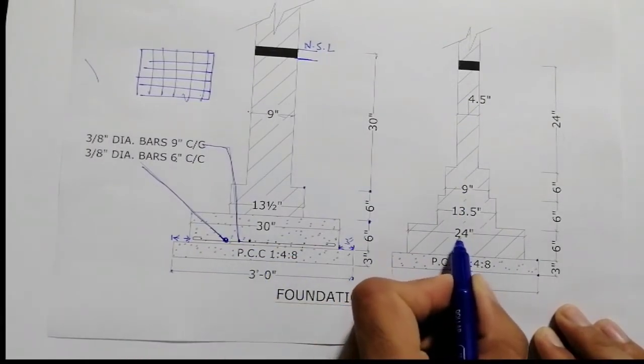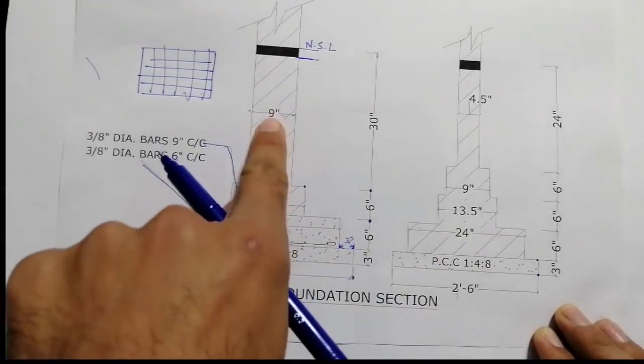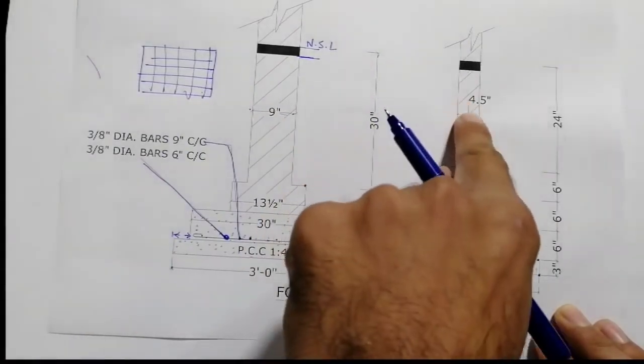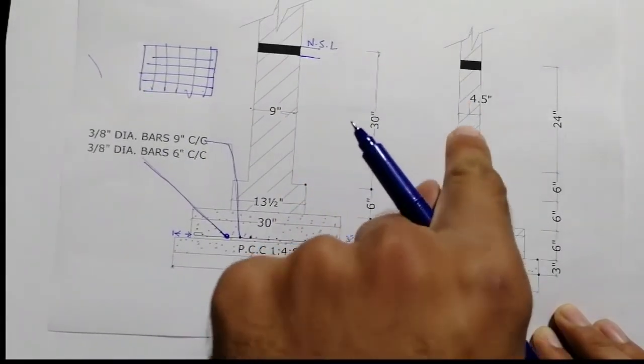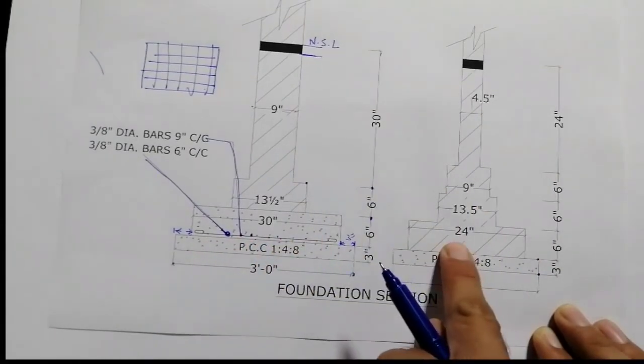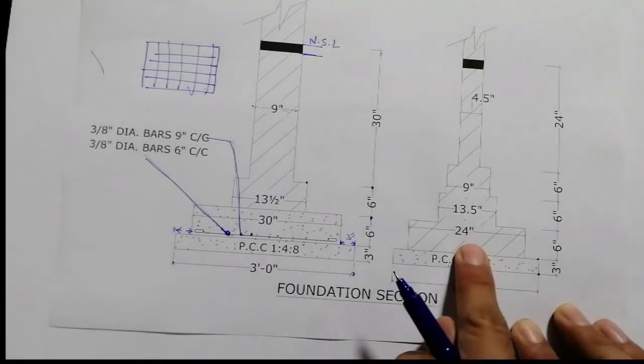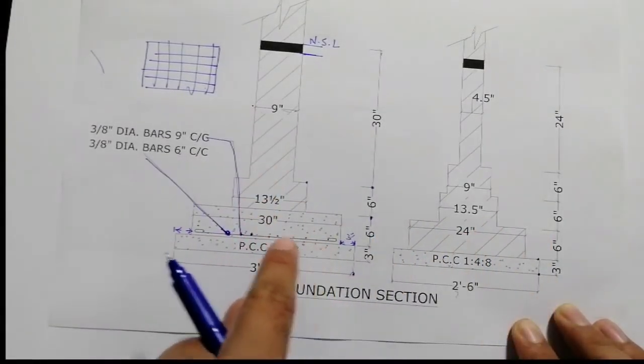But in second step, you can see here we didn't use any steel reinforcement because this is specially designed for 9 inches, so it's just 4.5 inches, so there isn't more load, so therefore we don't use reinforcement here because it will take more cost, okay? So it will become expensive, so therefore it's 9 inches, so we should use it here.